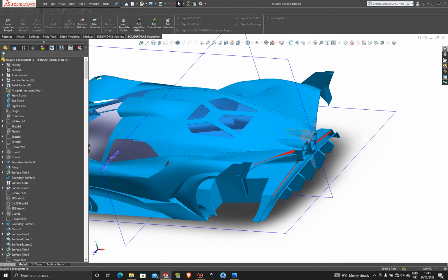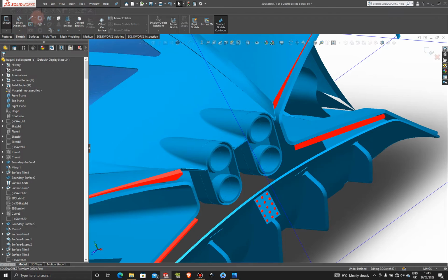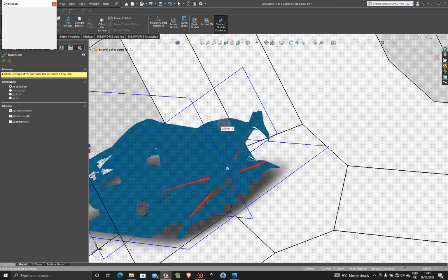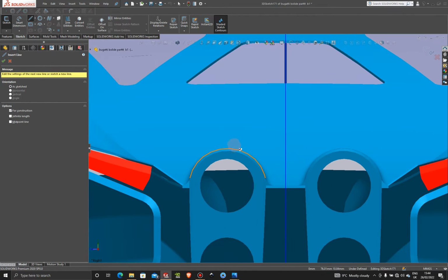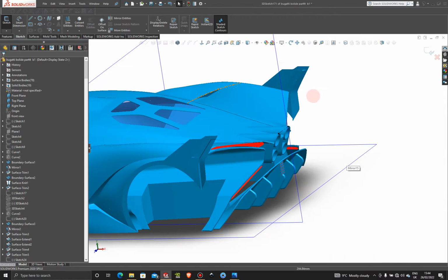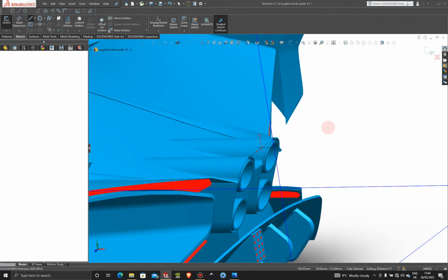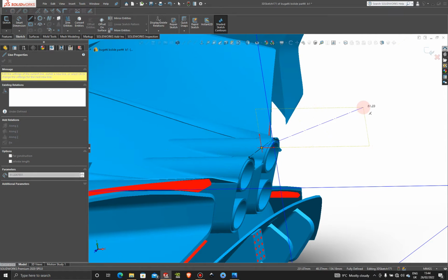So what we're gonna do here is, first of all, we're gonna grab a 3D sketch, of course, and that 3D sketch is going to be a center line, 3D center line. So let's be here for a second and just get into this view here. And we're going to drop a line in this midpoint here, from this midpoint to this midpoint, and then I just zoom out over here a little bit, and we're gonna drop another center line right on the middle of that line that we just created. And then we want to make sure that we are in the X and Y axis here. All right, so that will go straight up like that. All right, so X and Y, and you can change that by pressing the tab bar on your keyboard. All right, so let's just pull it up to here for now.